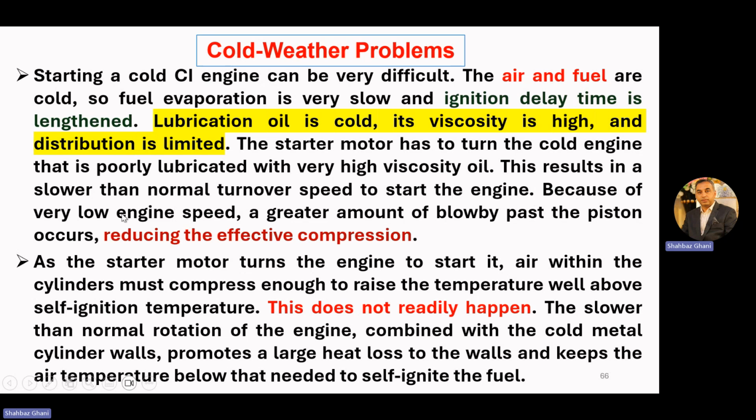Because of the very low engine speed, a greater amount of blow-by past the piston occurs, reducing the effective compression.